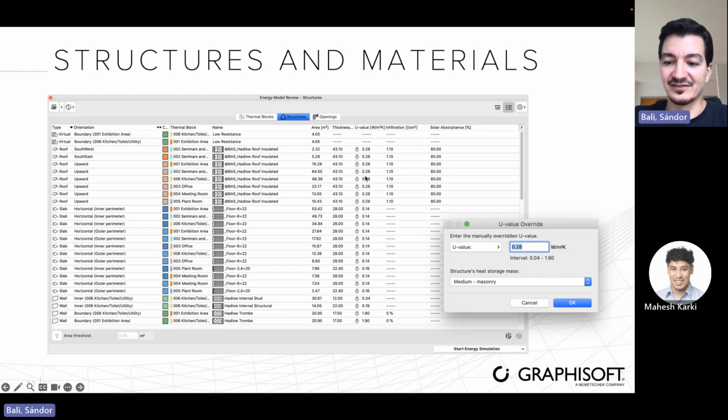What you would probably know about is the U values. And it's a very nice thing. What we can do here is that you can see that in our structures, actually, we have some very dedicated structures. So it means that you can see here it has different skins. So with all those physical properties, definitely it can be considered as a roof slab, as a flat roof slab. So obviously that would have a real U value in our calculation. And what happens here is that it can get calculated automatically. But what happens if I'm in the very early stage of my design and I just put there a structure which has no skins? Maybe it's just a 300 millimeter thick solid geometry, which I will define later. So how can I use this for the calculation if it's not defined? Well, when we are here in the structures part, I can come here to the U values.